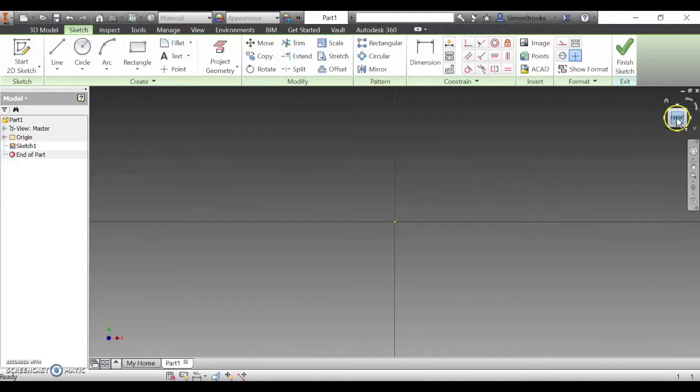For this particular pot, we're going to be creating a revolve. A revolve is just revolving a shape around in a 360-degree shape, or depending on what you're drawing, you could select a certain angle. But for this, we're just going to draw a simple concrete pot. To do this, our constraints with this drawing is 100mm tall or 100mm wide.